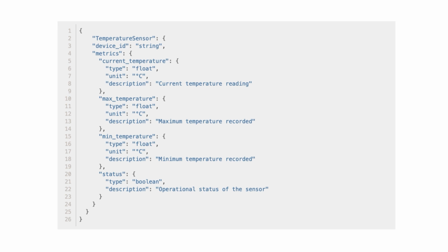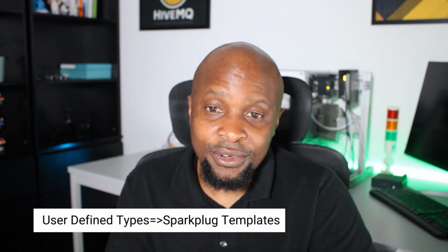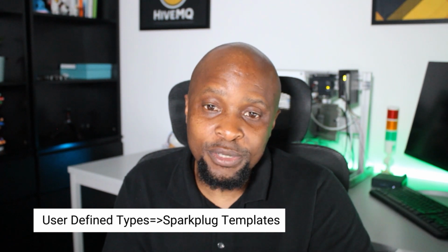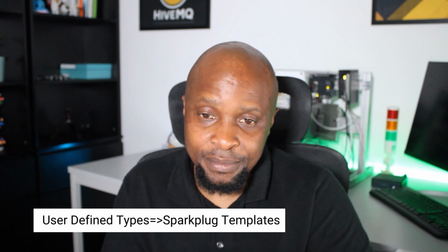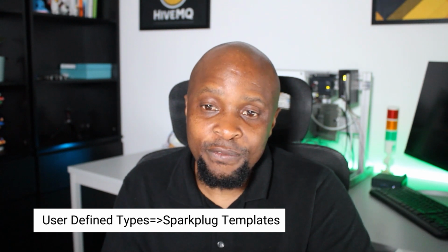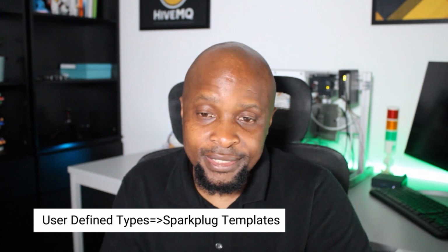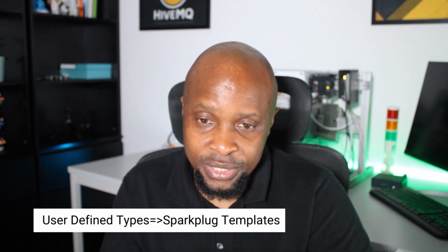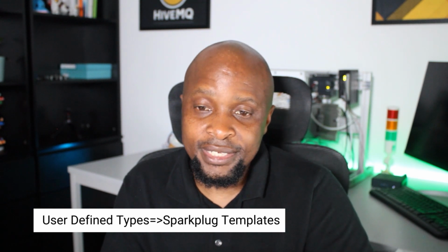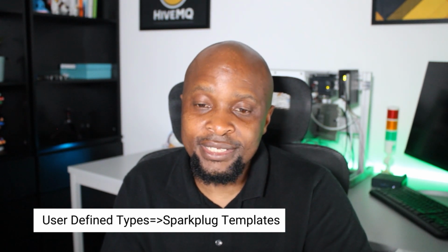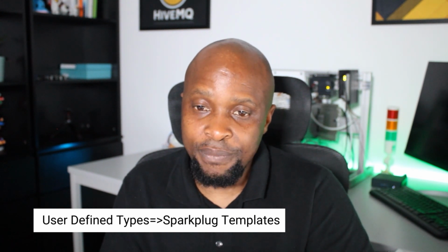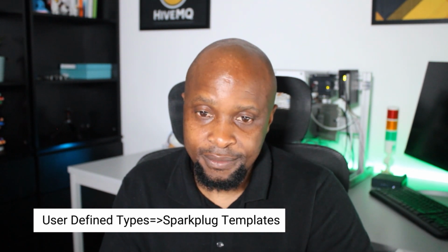Each metric includes a type, a unit, and a description. In SCADA or IoT platforms like Inductive Automation's Ignition, templates are formed by incorporating user-defined types. This process essentially involves publishing models and their instances that reference Ignition UDTs into the industrial IoT data infrastructure. These models and instances can then be dynamically utilized by other Sparkplug-enabled applications, facilitating seamless interoperability and data exchange.